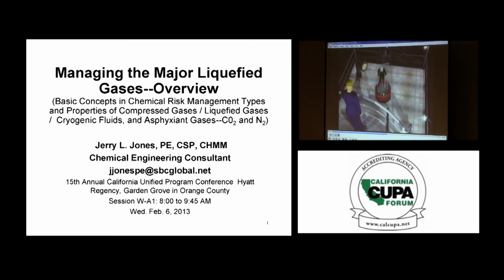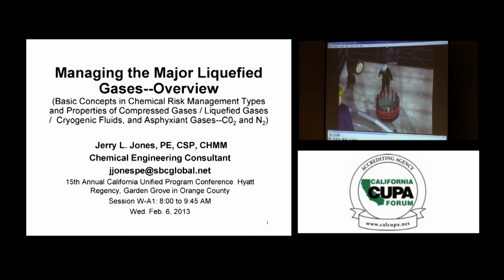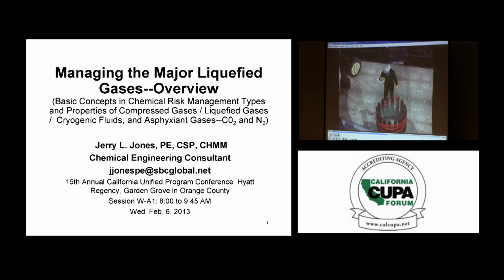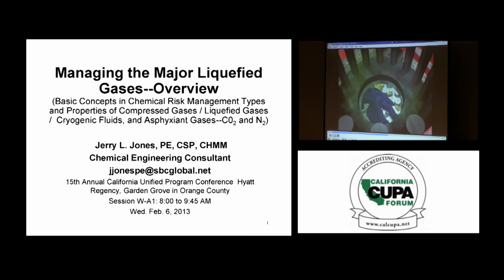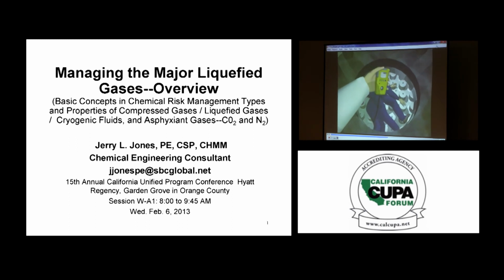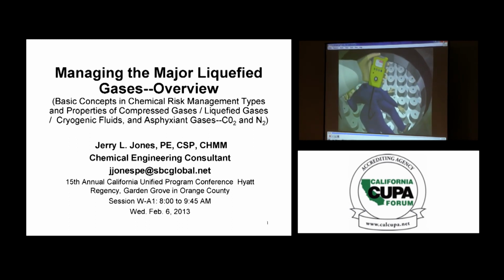The contract administrator declared an emergency on his radio. Valero operators then sounded the unit alarm. When company emergency responders arrived a short time later, they saw both victims lying motionless inside the reactor. A handheld meter inserted through the opening showed less than 1% oxygen, a lethal atmosphere.